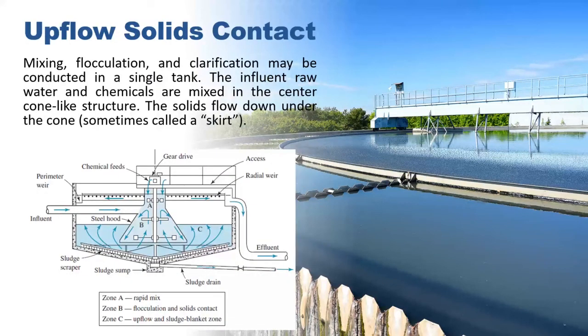Now let's move on to the upflow solids contact. Mixing, flocculation, and clarification may be conducted in a single tank. The influent raw water and chemicals are mixed in the center cone-like structure, so the solids flow down under the cone, sometimes called a skirt.